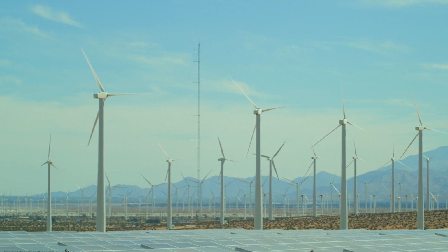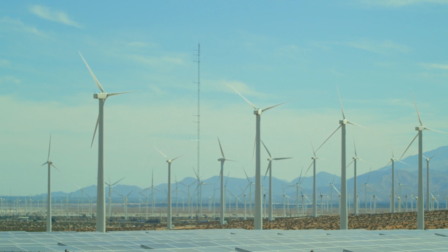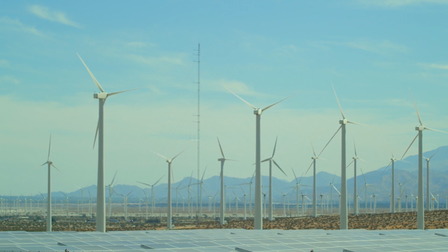We use WindPro tools to design the layout of our wind farm. We need to place the turbines on the terrain based on factors like wind direction, turbine spacing and terrain characteristics. WindPro provides visualization tools to help us see how the turbines will be placed on the site. Then once all types of input have been given, we need to